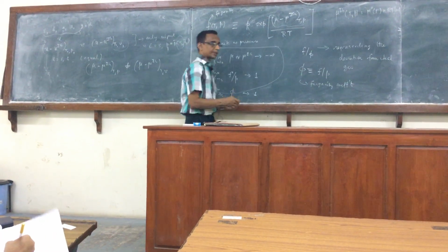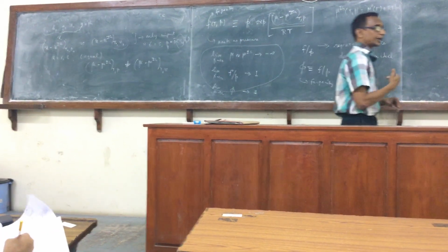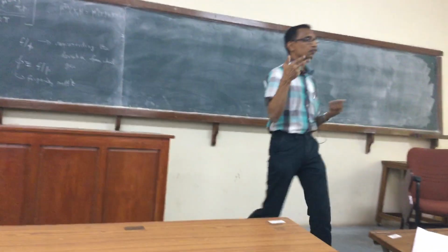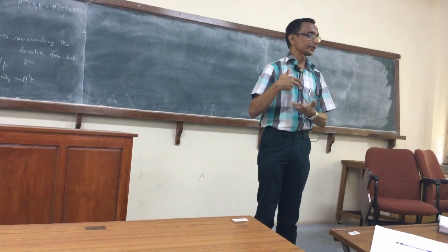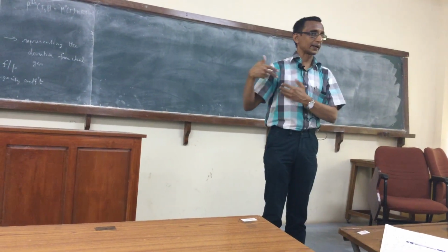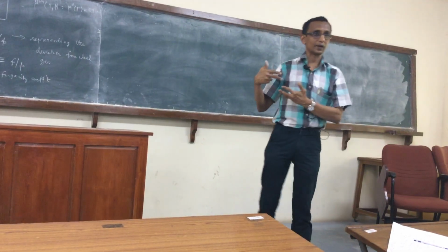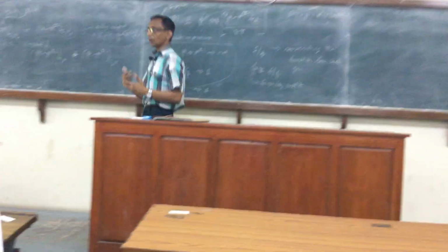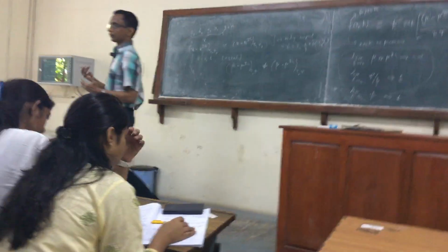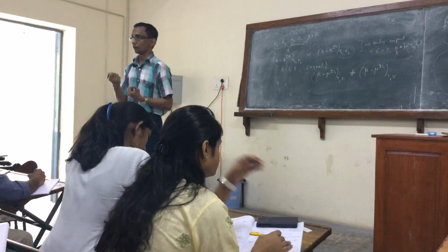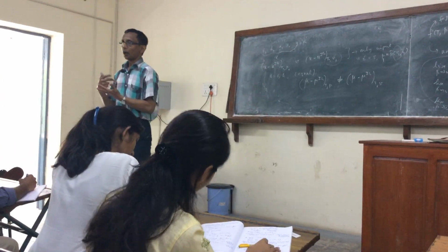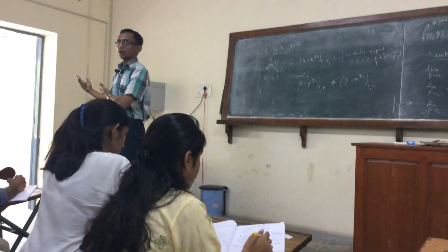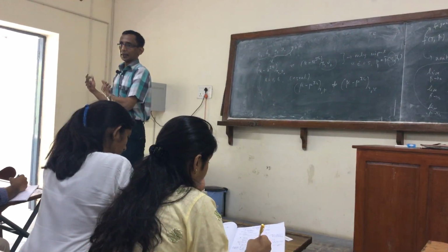By calculating the fugacity coefficient, we can determine how far the actual substance is from its ideal gas behavior. So that is another important significance of the fugacity: with just one number, it gives a measure of the deviation from the ideal gas behavior.